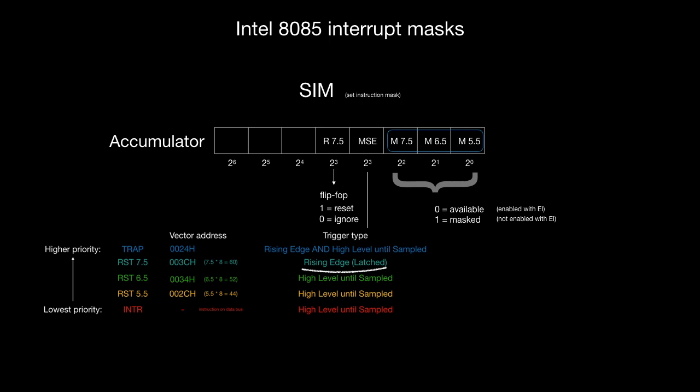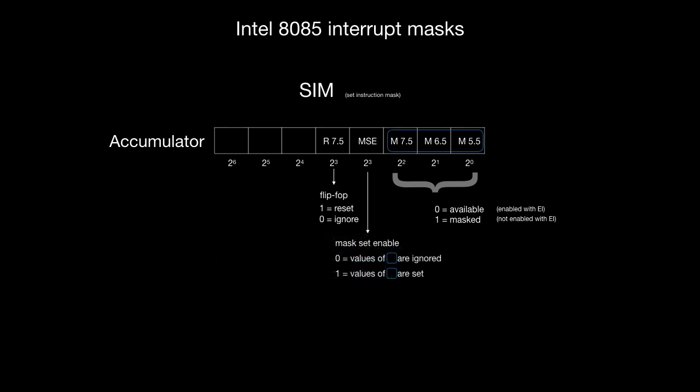So with this bit, you can reset, you can clear the pending interrupt. The next bit is a don't care bit, so you can put in whatever you want. Generally you will use 0, and the highest bit is the serial output data.